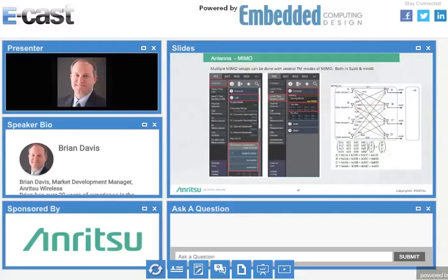MIMO capability, again, it's just simply going into the GUI, setting up what kind of MIMO you want to do. We support multiple transmit modes, TM3 up to TM10, 11, 12, to test parallel redundant streams of data. This is just a propagation matrix for MIMO, 4x4 MIMO there, so you've actually got parallel data going across the different antennas, but that's not always the case. Maybe you want to have different data going across different antennas for greater throughput.